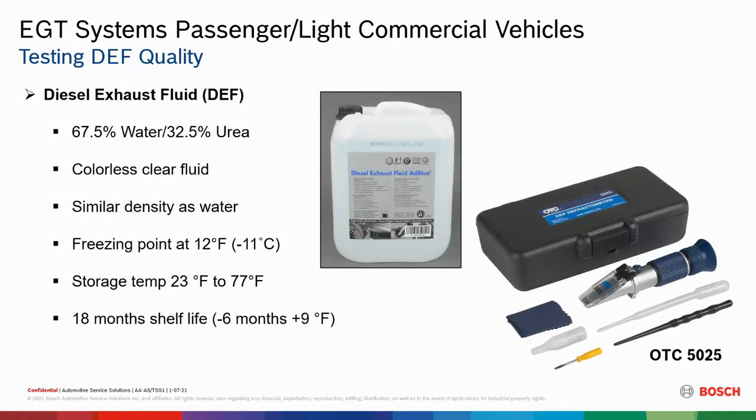But anyways, DEF fluid is 67.5% water and 32.5% urea. It's synthetic urea. No cats were harmed during the making of DEF fluid. I honestly believe that. Anyways, this isn't a science class or anything. All DEF manufacturers have to meet this quality here. So it's deionized water and synthetic urea. If it doesn't meet this standard, then we're definitely going to have problems.